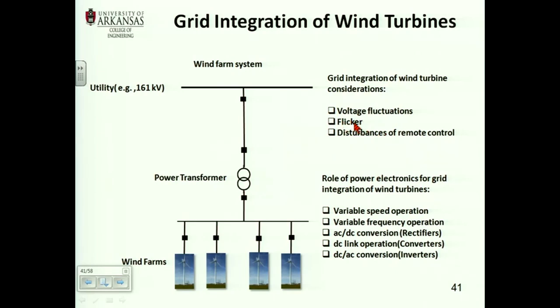Now what is flicker? Flicker normally is concentrated at frequencies under 8 to 10 hertz. So if that voltage fluctuation is sort of periodic and at a frequency under 10 hertz, you are going to notice. If this is at 1 kilohertz, your eyes are not going to see it. So it has to be very low, slow-moving changes of the voltage.